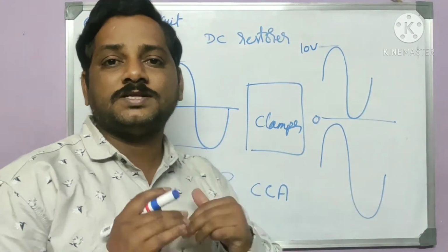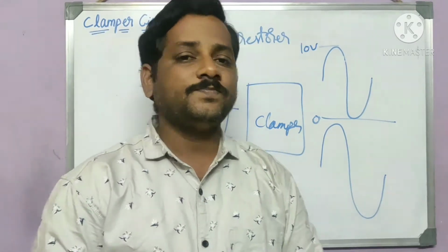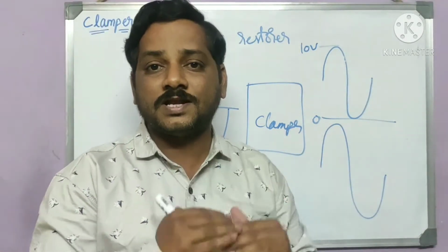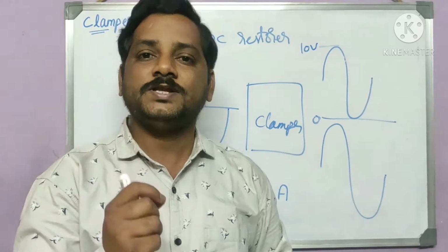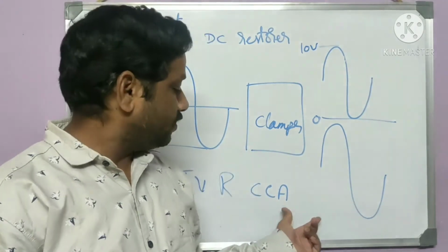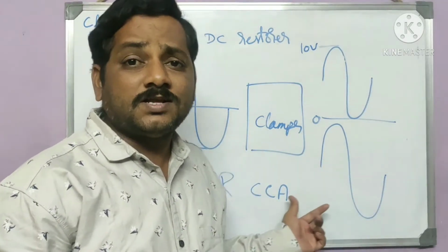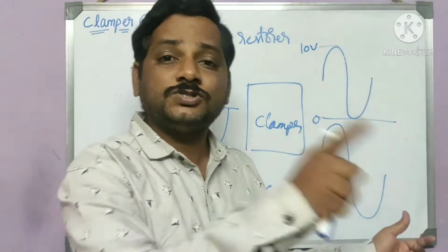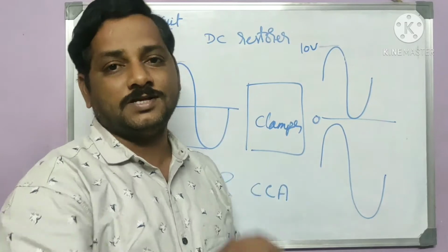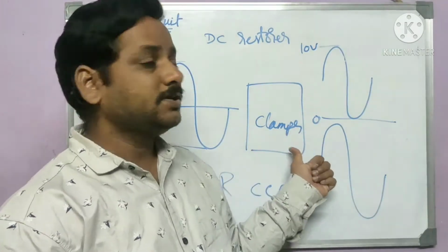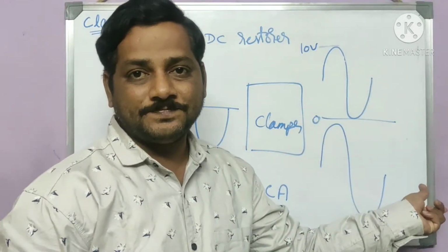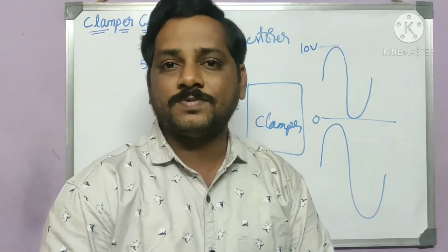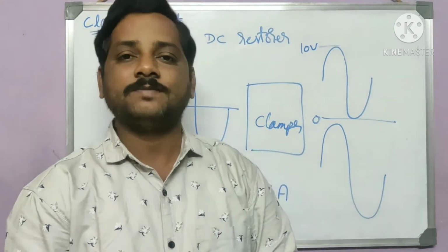Right? It blocks the DC component. But generally, to have black and white reference lines on a television, we need that DC component. So after this amplifier, the DC component is blocked because of the capacitor. But I want to restore that DC component into the signal. So there I use this clamper to restore the DC component. That is one example or application where we use this clamper circuit.